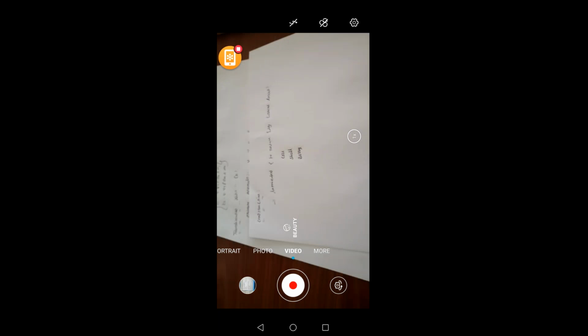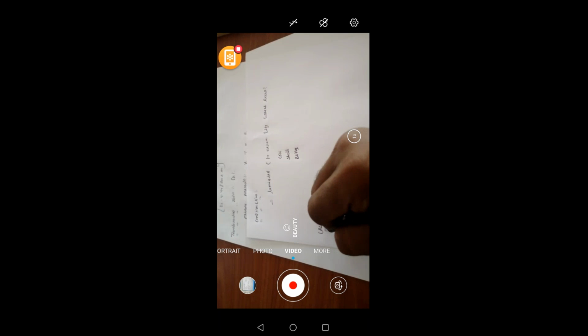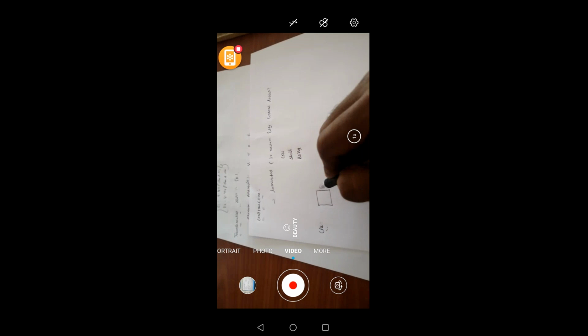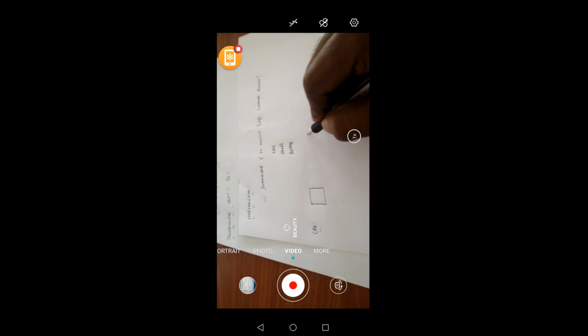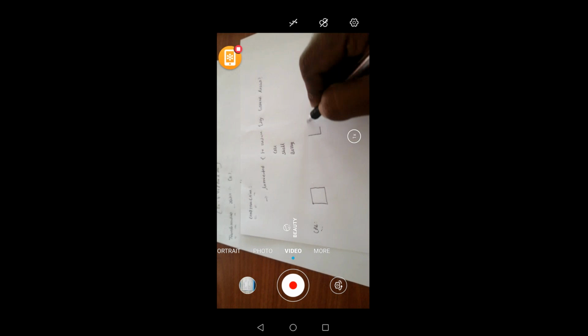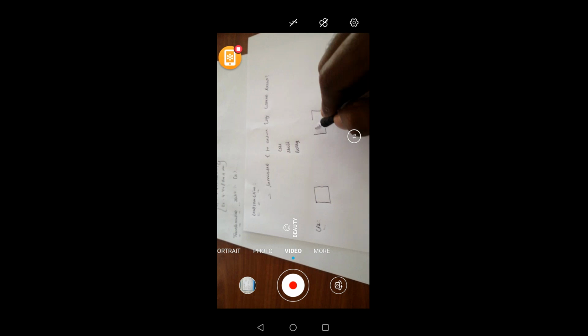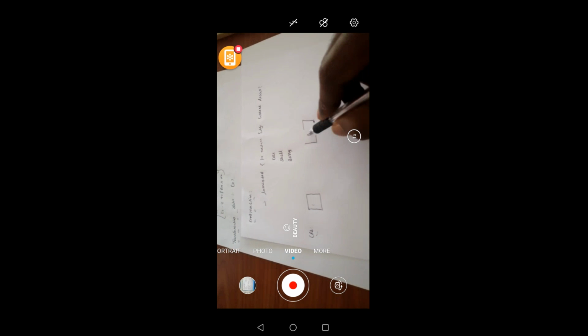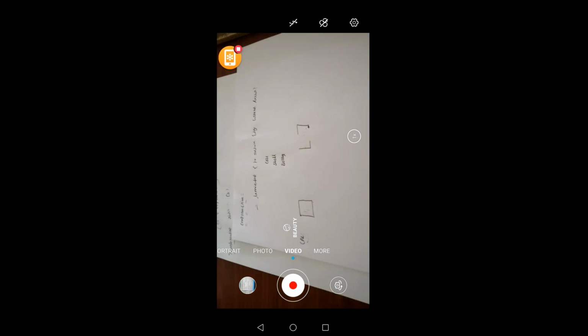Now suppose you want to design the core type transformer. The full structure should be like this, but they are considering a number of plates like this. So they are cutting these plates like this, and finally adding them, so you will get the structure like this. They are cutting that core in L shape. After these two L shapes are added to each other, you will get the final shape like this. The materials used in the construction of a transformer are cast iron and silicon steel.